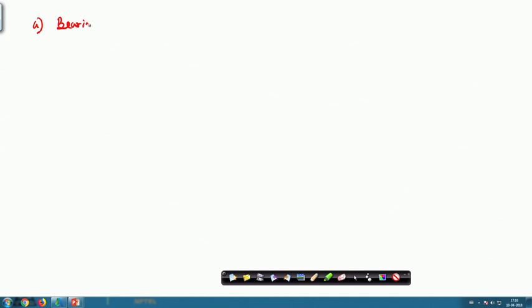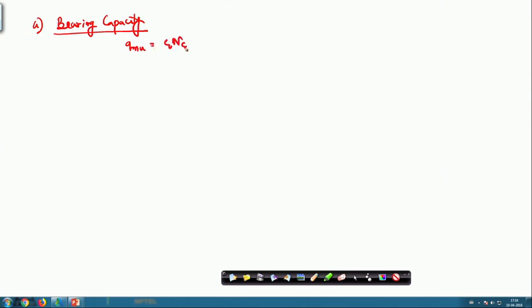So now the first check is the bearing capacity, and again this is for the Cu soil only. I will take q net ultimate as Cu Nc, and I will take the Skempton expression that I used for the isolated footing also.